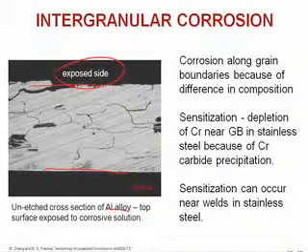It wasn't etched. So you've been looking at etched microstructures. Etching is a corrosion reaction that brings out the grains. This was not etched. It was just cross-sectioned. And we see that just by cross-sectioning, there are gaps, regions where corrosion came in through the grain boundaries. The grains are unattacked.